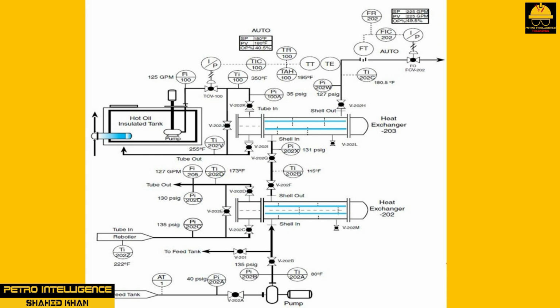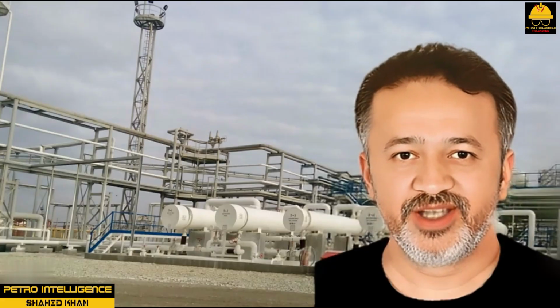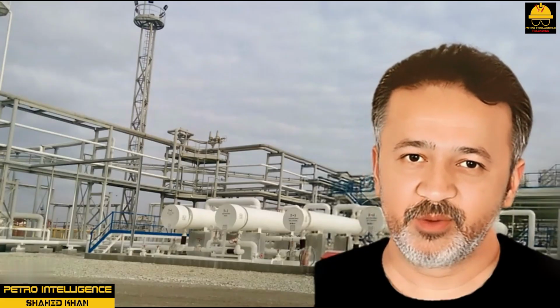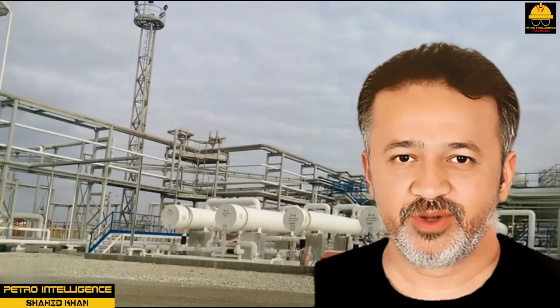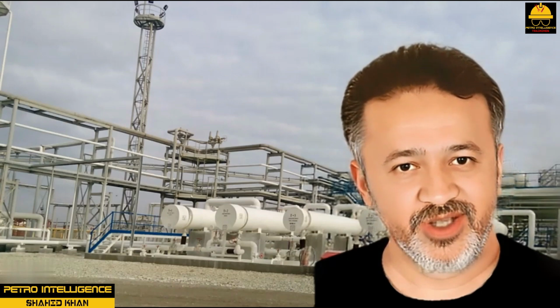A flow control loop is found on the shell outlet of X203 and fails in the open position. This will prevent the feedstock from overheating and potentially rupturing the heat exchanger. Correct lineups on heat exchangers are essential, and process technicians should carefully review the standard operating procedure.